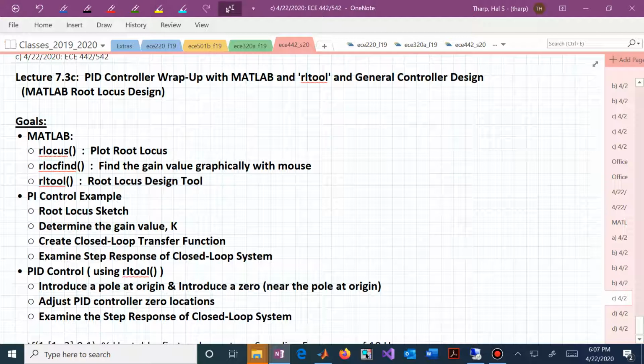That means that we need to introduce another 0 and the second pole, the pole at the origin, and we'll slide that 0 a little bit off of that pole so that we can hopefully produce a root locus diagram that has our closed loop poles at Z delta locations that are more desirable for percent overshoot, settling time, behavior, etc. In both cases, with the PI or the PID, because of that integral action, they both better give us and will give us steady state accuracy in the form of 0 error due to a step.